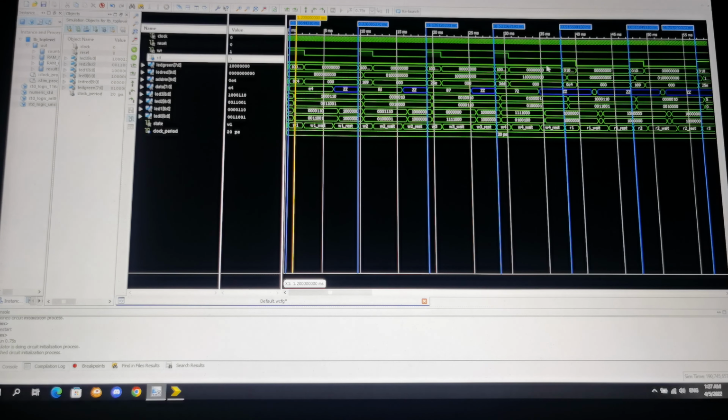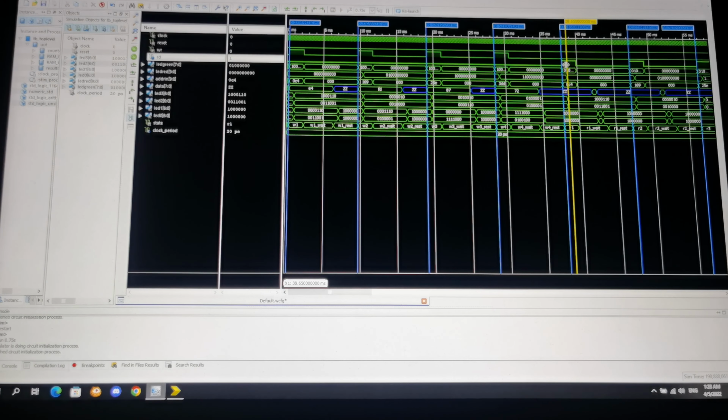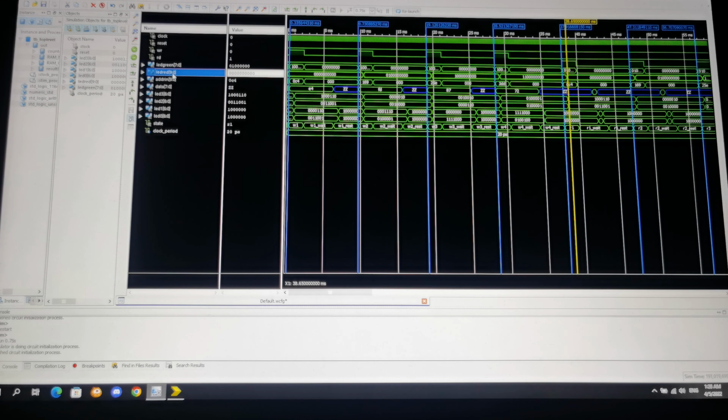The same goes for the read operation. In the read operation, the signal WR is 0 and the signal RD is 1. The result LED shows 0 1, which means 0 is WR and 1 is RD. This will be shown on the Altera board. The red LED is just showing the memory bank used.